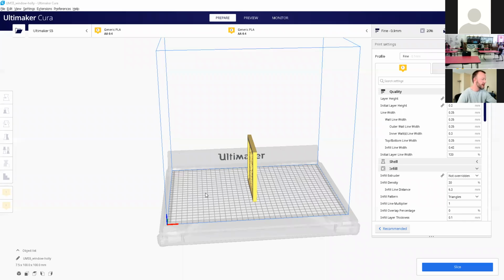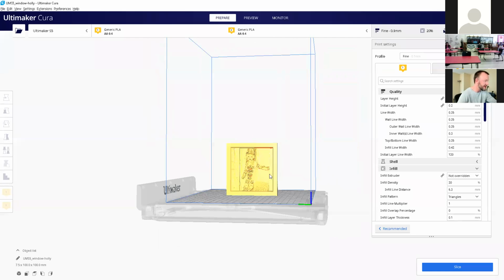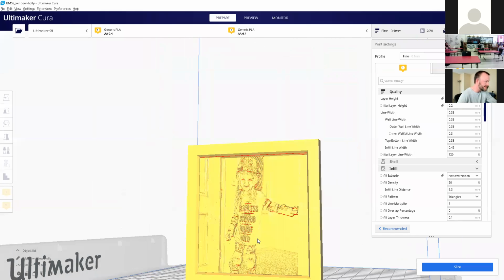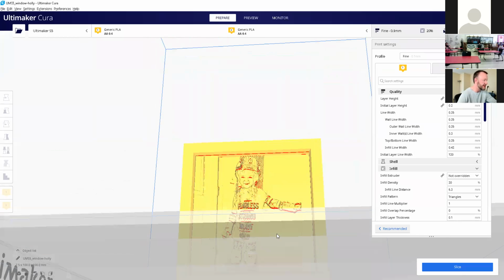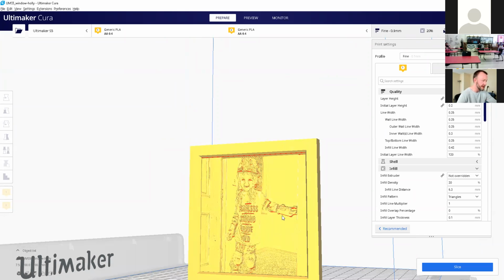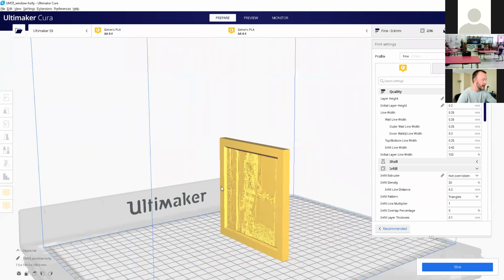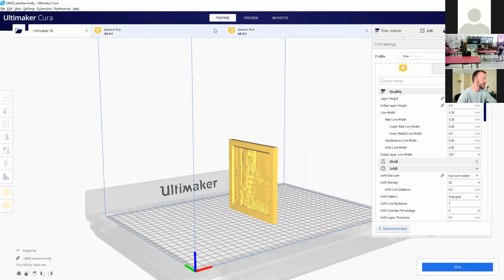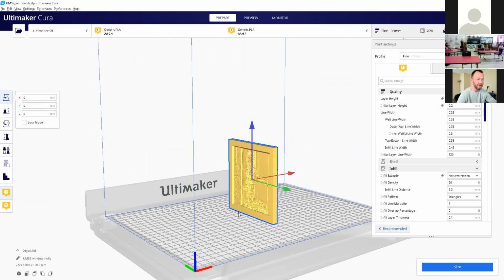All right, so this is what it generates. This is the STL file that it generates. You can kind of see sort of what it's supposed to be, but again, the idea is you don't see anything until it's actually backlit. You can print this just like this. It is fairly thin, and when you print objects like that, there is the possibility that it'll detach from the print surface if there's not enough to stick it there. The printers that you guys have glass plates, so it shouldn't be an issue.